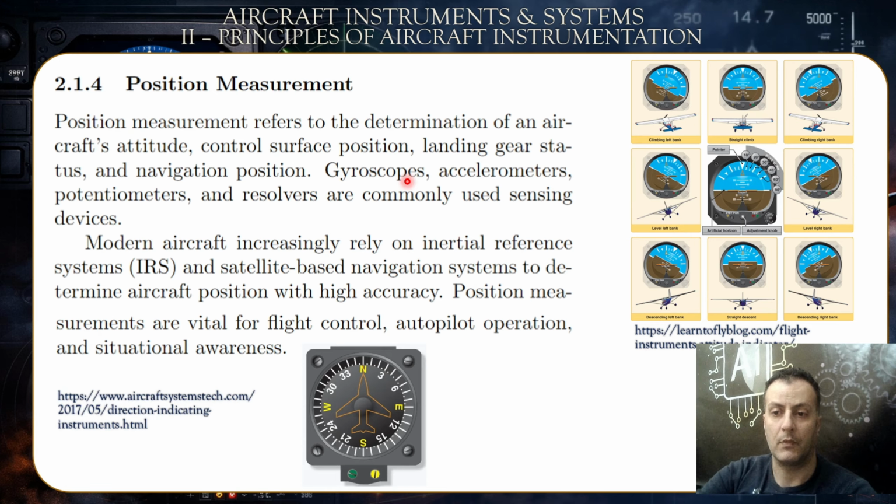Also, as for the pitch up and pitch down, the same thing. As the aircraft is pitching up, you have the accelerometers and potentiometers that resolve that display, to give you situational awareness whether the nose of the aircraft is up or down. If it's up, it means it's like this, usually during a climb, but not necessarily during the landing. It would be pitched up, despite the fact that the aircraft would be descending.